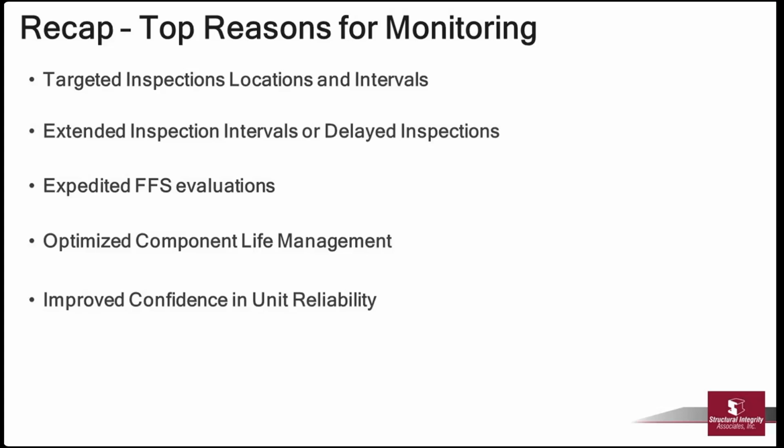Do you think on an evaporator riser or tube bends in an economizer, this would be applicable? I'm thinking of monitoring FAC progression or damage. Definitely, it could potentially be an option there. I'm not as familiar with those specific components, but if it's something that you would typically do ultrasonic thickness inspections on, it could potentially be an option.